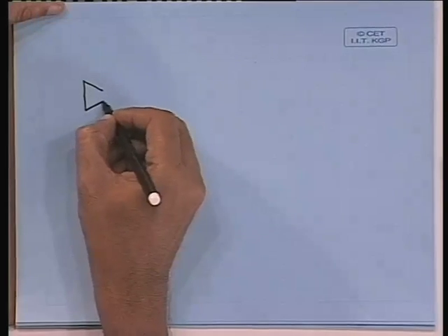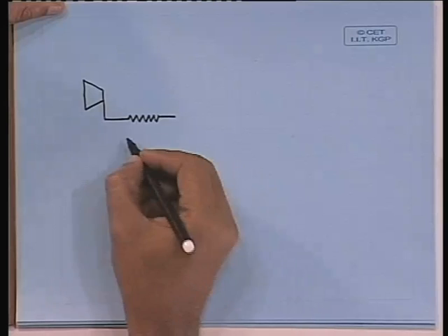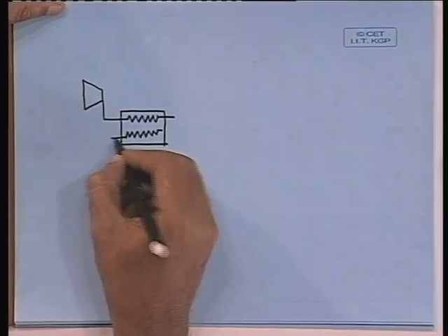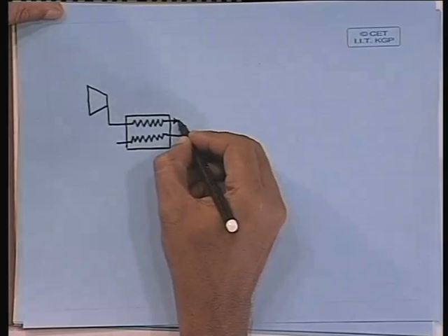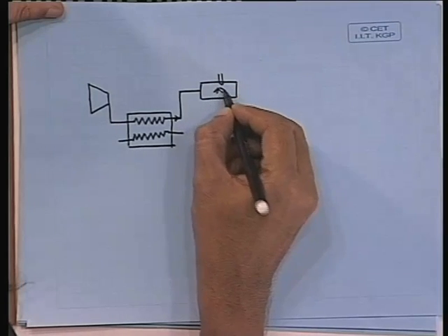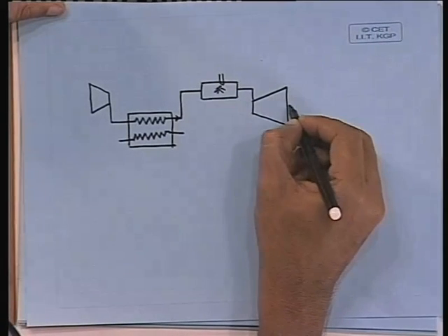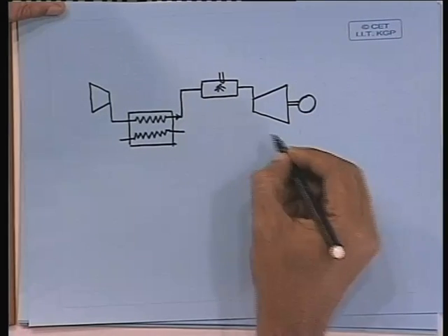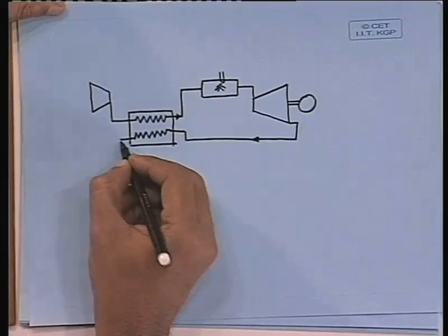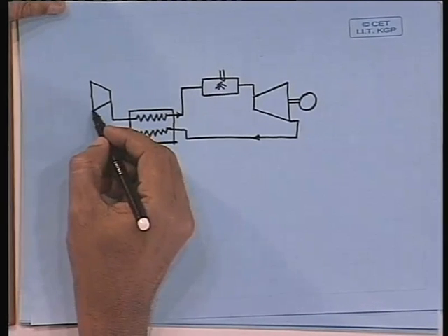First the compressor, then from the compressor the stream is being preheated, then after that it is going to the combustion chamber, where we have got fuel spray, then it is going to the turbine which is generating power, then this one is the exhaust gas, and ultimately through the regenerative heater it is going to the ambient atmosphere, and this is again ambient atmosphere.